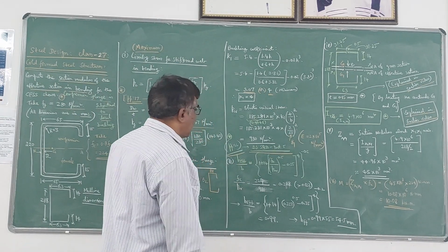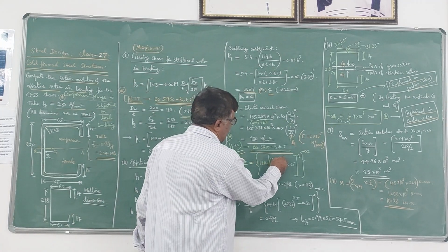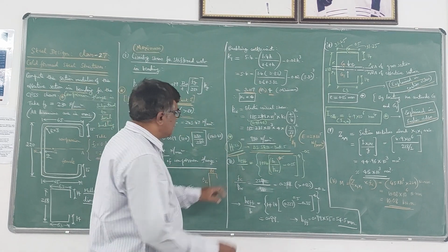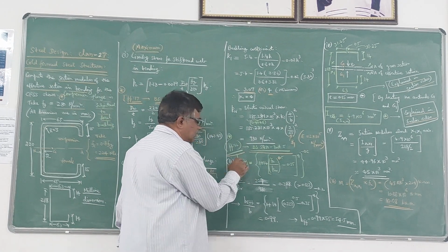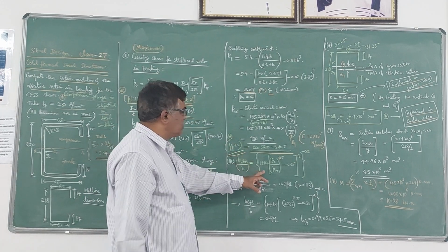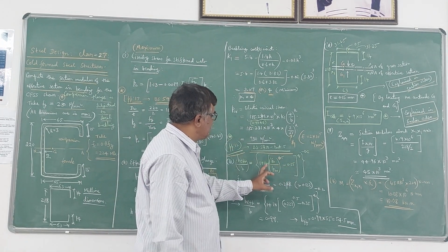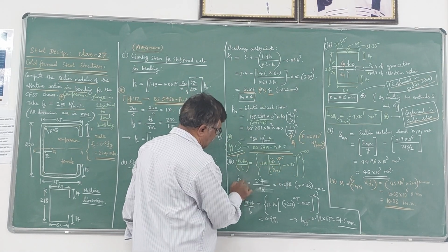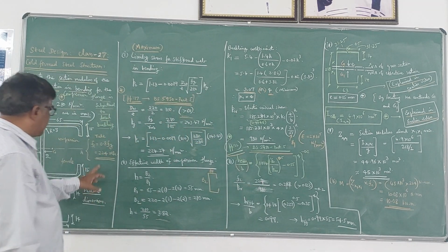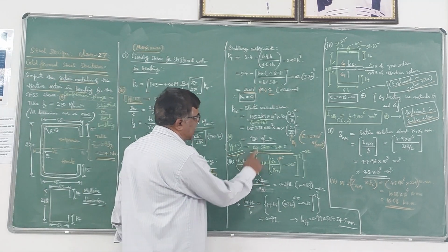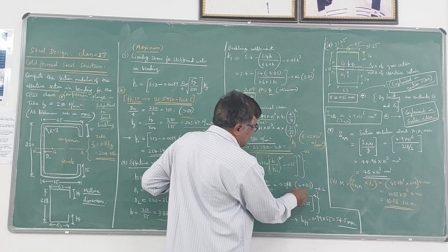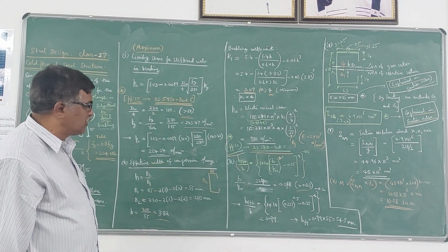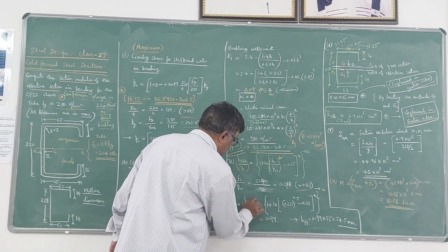Now after having these two values, FC and PCR, we have to calculate this ratio B effective divided by B. It is available in page 12 of the British Code, Part 5. Use this equation here. You know all the values in the RHS. So I will calculate FC by PCR now. FC is 224, divided by PCR, which is 980. The ratio becomes 0.228. So you have to compare that ratio with this value 0.123. Since it is greater than 0.123, this formula we have to use. That's what the code says.